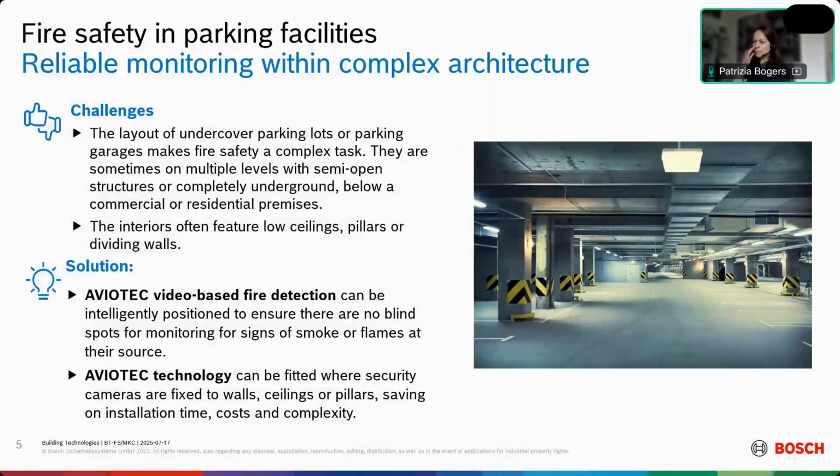First of all, the mentioned complex architecture. We often deal with several levels of parking garages, often connected to a commercial or residential premise that also needs to be protected, of course, in this context. We have different height of ceilings. We have pillars in between, dividing walls. So yeah, we need to find an answer in the context of this challenging infrastructure to provide a proper fire detection. So AVIOTEC can be one solution, one answer to these challenges.